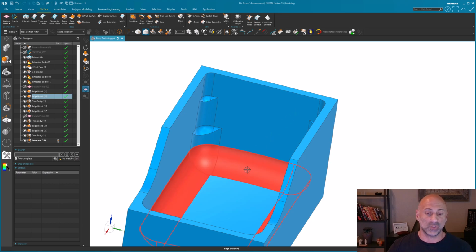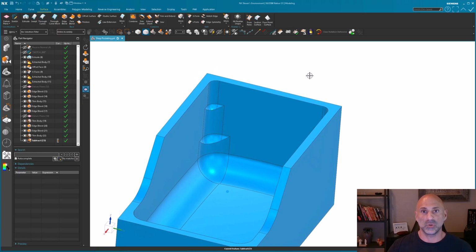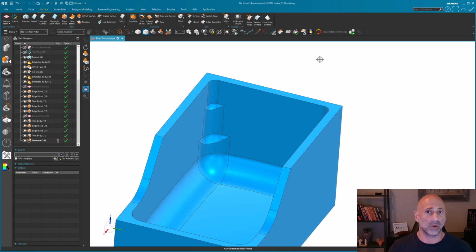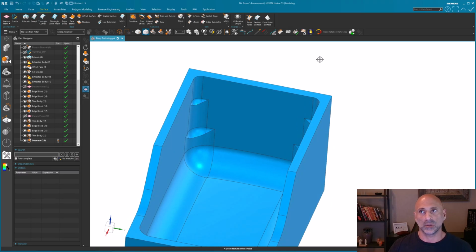So obviously if it's a gigantic cutter down here and you're going to step up, you're using much smaller cutters, you're going to remove a significant amount of swarf in that area. All that material is going to be chips on the ground. So that's one very important thing to consider, the length of the cutter.